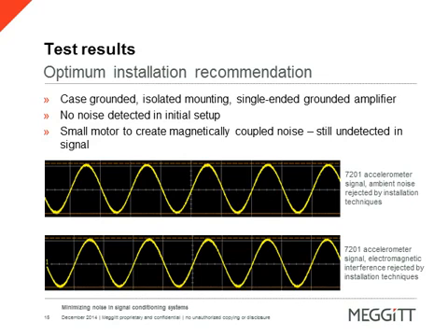The top sweep you can see is the standard setup, benign, before introducing the motor. Below is the motor introduced, and you can see we still have a fairly decent setup. Again, this is optimum, so any buildup of noise is bled back into the ground side of the accelerometer and isolated from the mount, so it keeps the electrostatic noise from getting into the signal.